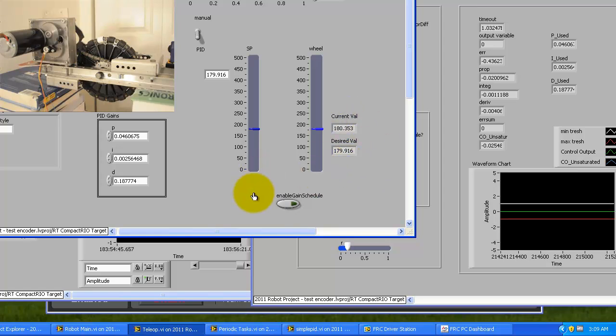So when you have an unbalanced load like that, a way to solve it is known as gain scheduling, where you use multiple sets of gains for different scenarios. The algorithm that I put together has the ability to accommodate two scenarios. One set of gains for when your set point is greater than your current position, and another set of gains for when your set point is less than your current position. So for example, if I were moving an elevator and my set point was greater than my current position, that means it was going